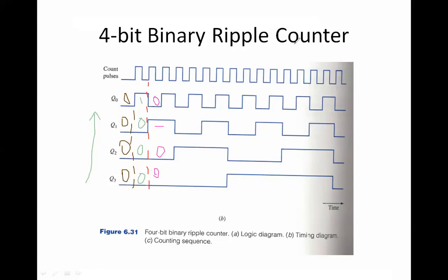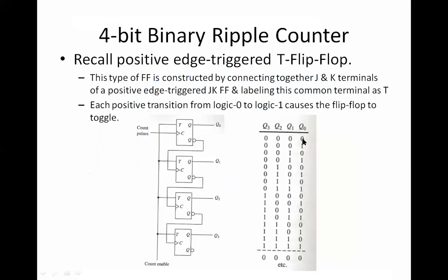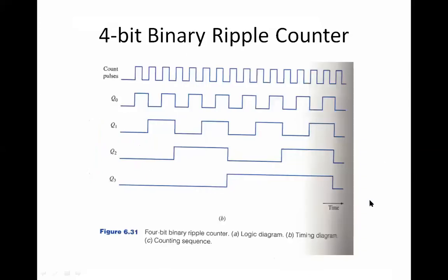So this is how you can actually break up into each positive cycle, and put these values and understand as to how we are getting them. So ultimately we will be getting these values 0, 1, 2, 3, 4, 5, up till the high value. So once the high value comes, then again we can reset it, and then we get the values 0, 0, 0. So this is nothing but your 4-bit binary counter. So I hope you have understood this concept, right? Any doubts here?